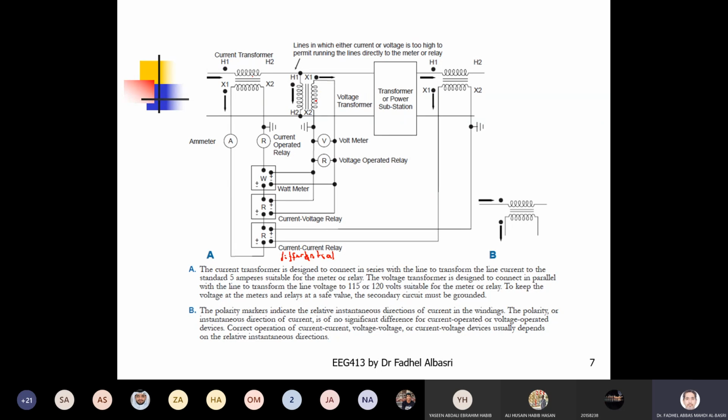And the second type of relay, there are some other relays. I can take the voltage output from the VT and measure that voltage. So a voltmeter can measure the primary side voltage. The primary side could be, let's say, 11 kV, while on the secondary I can use a voltmeter that has a range of, let's say, 600 volt or 400 volt. As I mentioned, the rated voltage here is 120 line to line. Now, this is a phase voltage, even less. So I can use a voltmeter to measure the primary voltage.